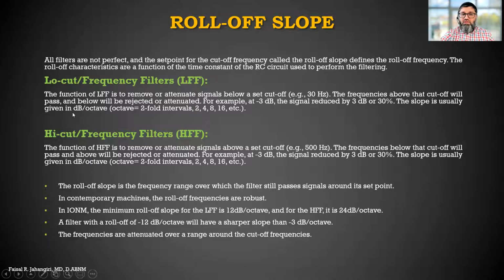The slope is usually given in decibel per octave. Octave is twofold, so that means 2, 4, 8, 16. So the slope is given in decibel per octave.